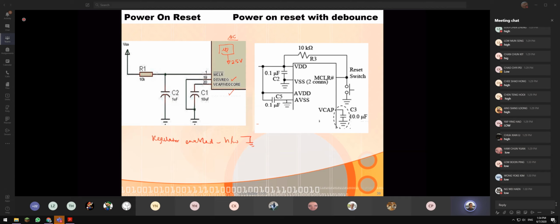Once this is enabled, you are telling the microcontroller that the microprocessor is operating at 2.5 volt. This indirectly links to something called BOR, brown out voltage. Class, I hope that you are making notes for yourself as well. In PIC18, brown out voltage can be set through the config register.